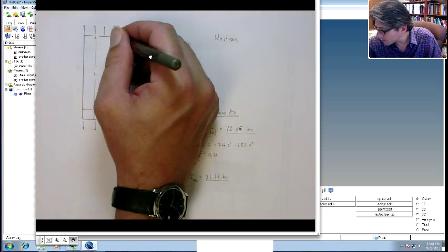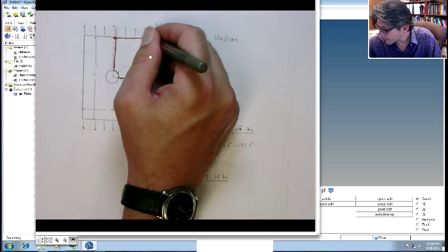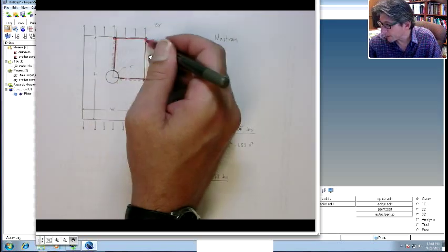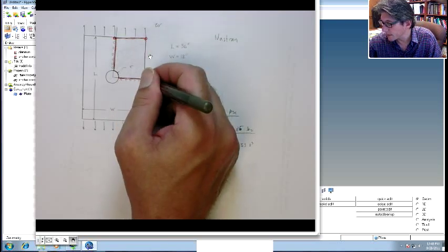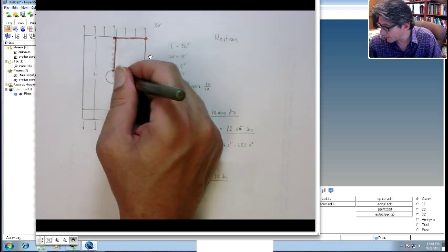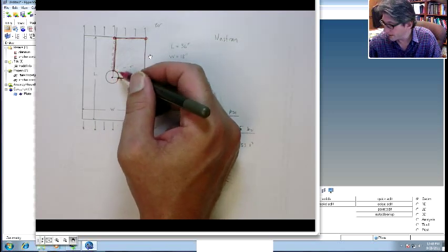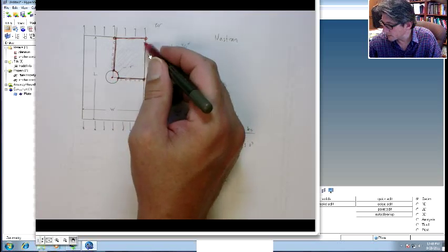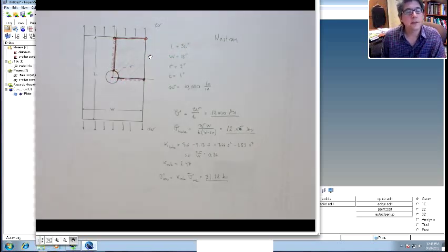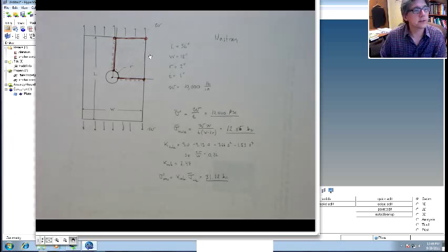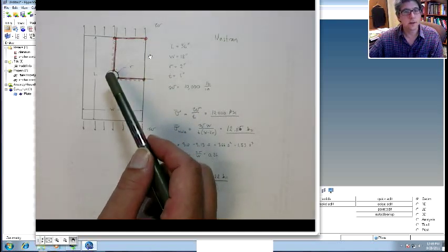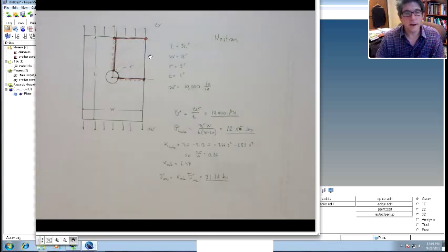And then to define the curves, you actually need to define the points. So for example, to draw a line from here to here, we need to define points here, and likewise for this edge. So I'm actually going to need to define some points as follows. So I'm going to define a center point. I need that to make this arc, and then we'll put points at all these sort of corners here like this, okay? Once I make the points, and actually Hypermesh calls them nodes, they're not necessarily the same nodes that go onto your mesh, then we'll connect the points using line and arc or a circle, and then once we have the bounding curves, we'll mesh it, okay?